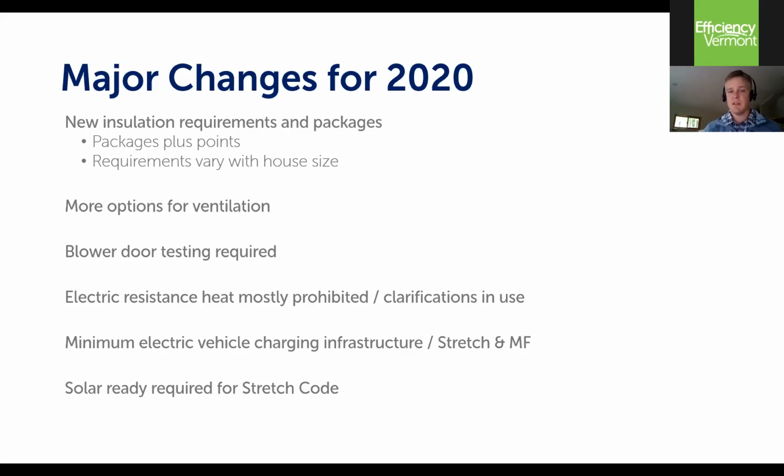Electric resistance heat is mostly prohibited now in the code. There are some clarifications where it can be used, which can come into play. Minimum electric vehicle charging is starting to be a factor in the code as well. This comes into play for stretch code compliant projects as well as multifamily. It's not a standard requirement for single family residential homes at this time. And then as well, solar or PV ready components are required for stretch code as well.